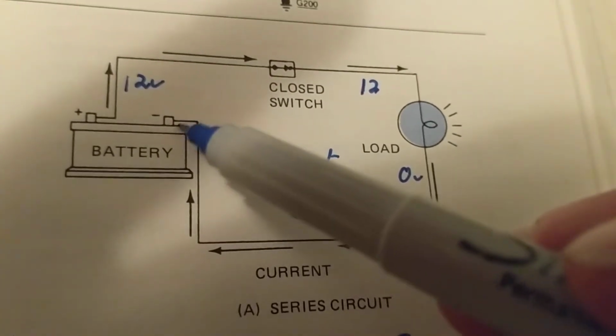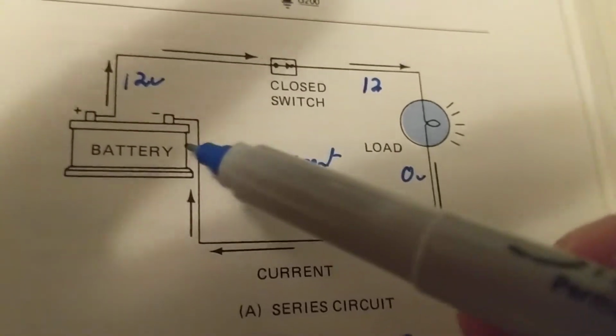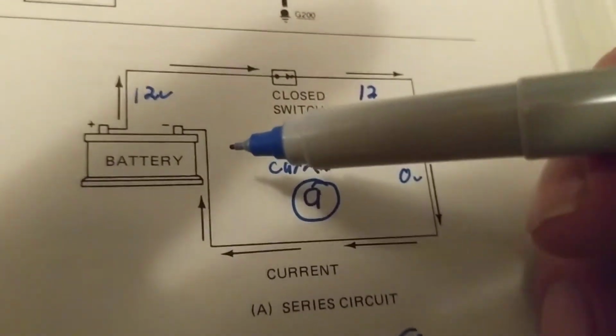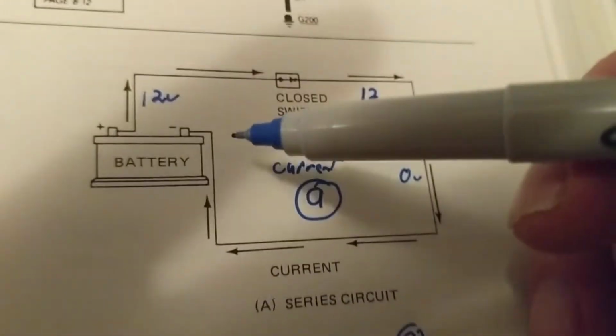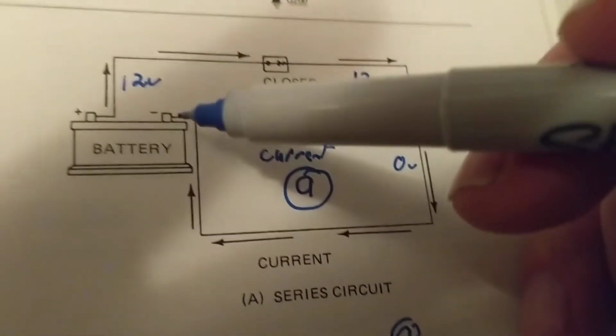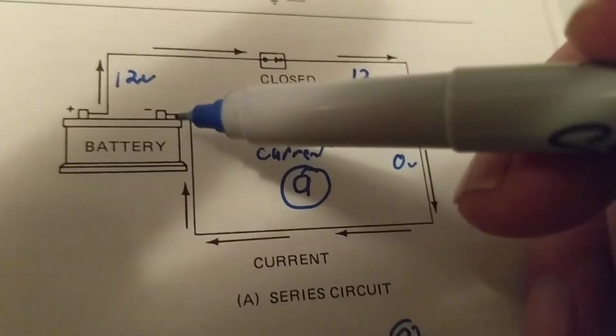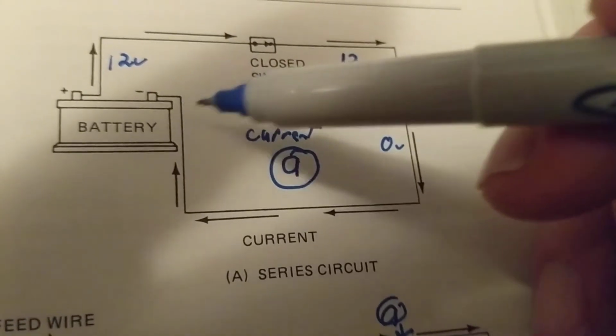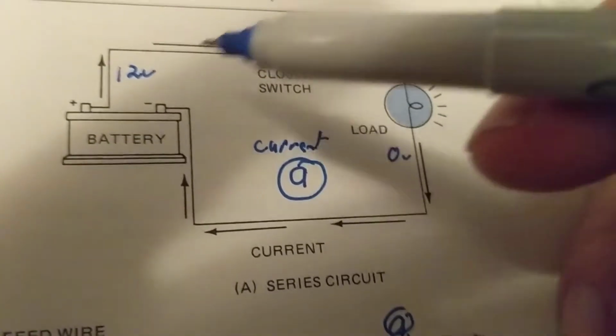We need this to be connected to negative. This negative goes sometimes to the engine block, which you will see. So if you have a problem sometimes, let's say the lights don't come on or the power locks don't come on, make sure that the negative is tight. Make sure you don't have corrosion and other things and rust around the battery terminals, like you'll see when we go outside.